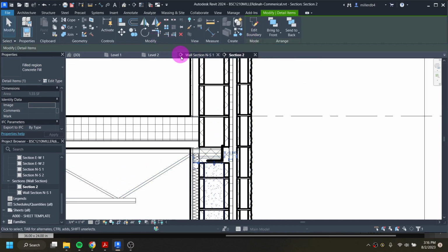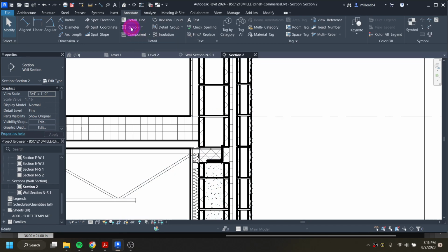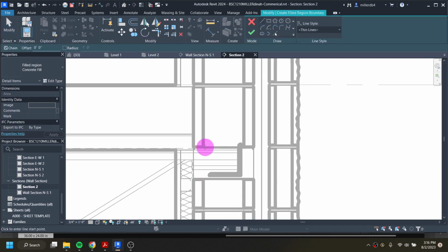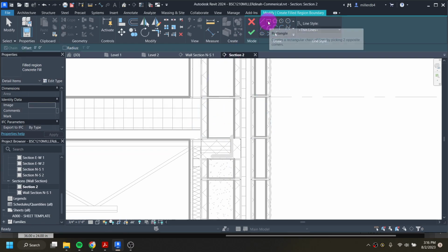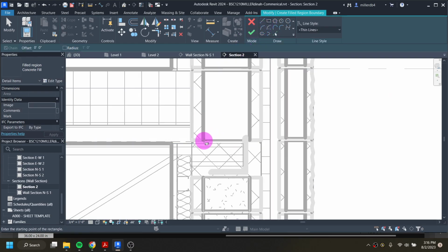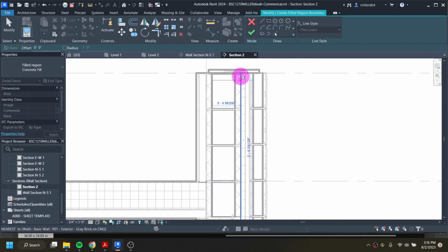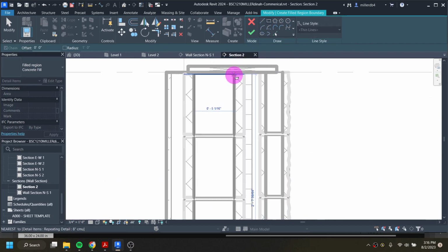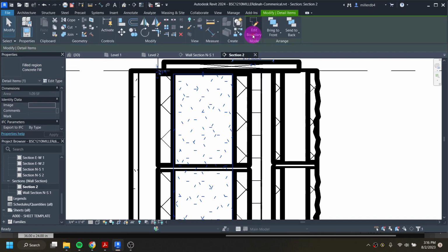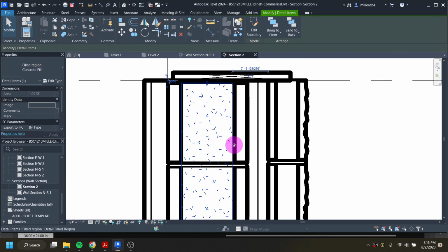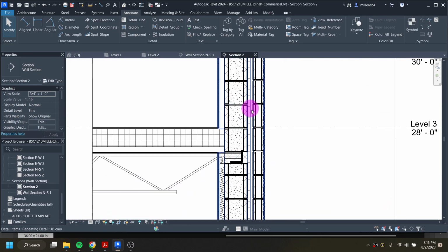And then I'll hit escape a bunch of times and do another filled region from here. I'm in the line tool. I keep forgetting it doesn't put me in rectangle automatically. All the way up to here. And then, okay. I'm not too worried about if it's on that line or inside that line because the line weight's going to take care of that for me. But this way, then I have it filled with that concrete pattern.